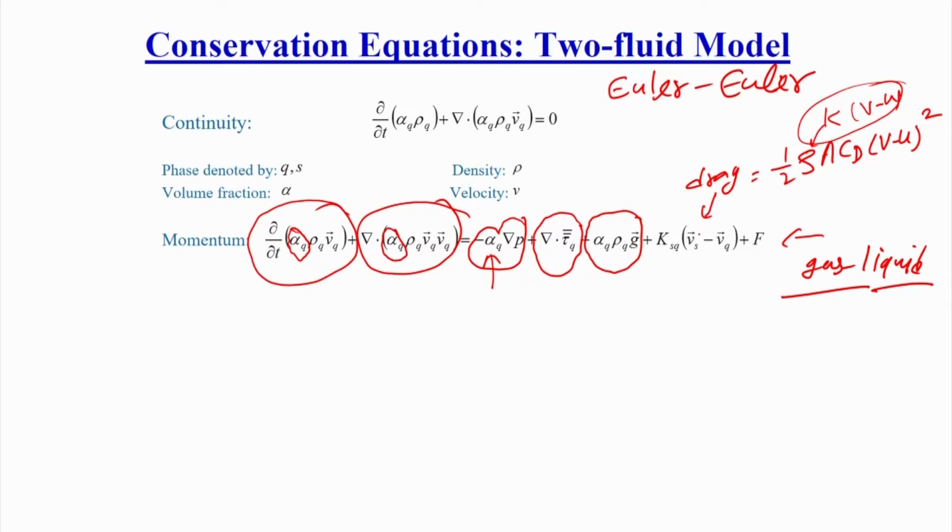If you have any other interaction forces, like virtual mass force, or if you want to use the lift force or any other force, you can also include it here to solve this equation. So that is what we do in the two-fluid model or Euler model.